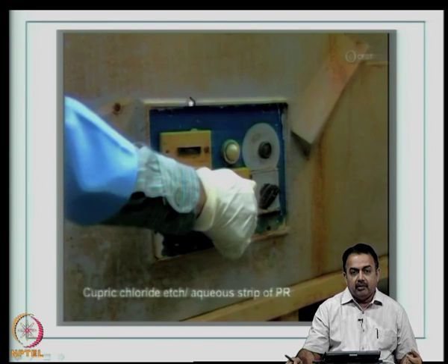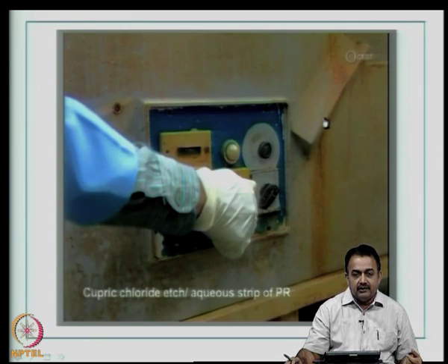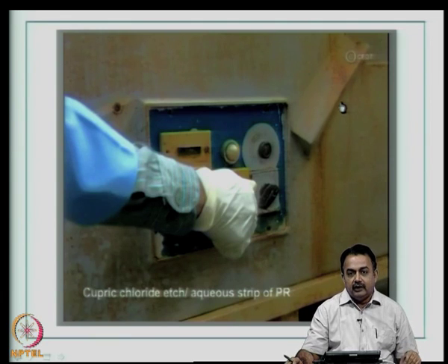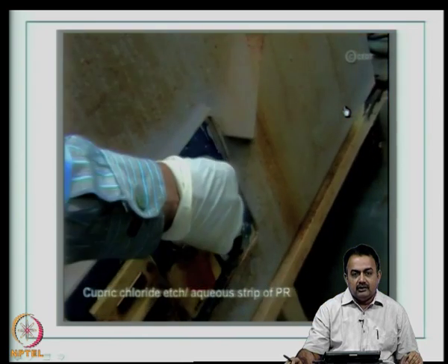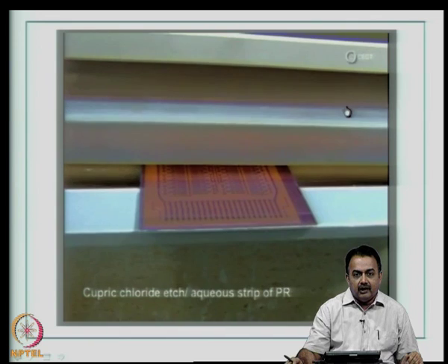So, after etching, the important process is to remove the photoresist which acted as an etch resist. You can see here the etchant is a very corrosive chemical. Even the equipment that you are using, in this case it is actually a PVC material, even then you can see that the leakages from the spray of the etchant and the fumes that come out from the conveyorized etching machine or the batch etching machine will create a lot of corrosion. So, personal safety is very important, and also you have to look at how you can save the equipment for extended life.